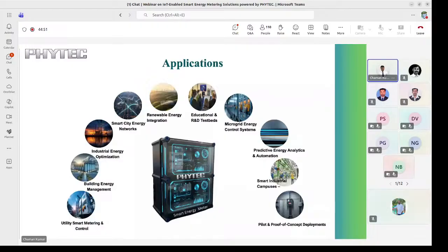This is the dashboard where I will read the data, instantaneous values, and from here I can also control the load. I also implemented some AI script over here to protect the data and the system. If the voltage is greater than 270 volt, it will turn off the load automatically, and that will give protection from the supply side.